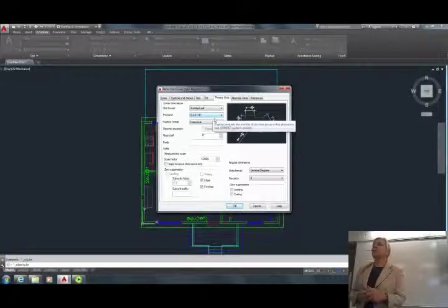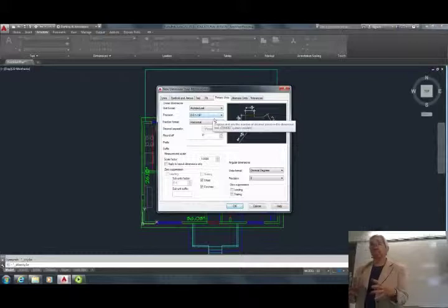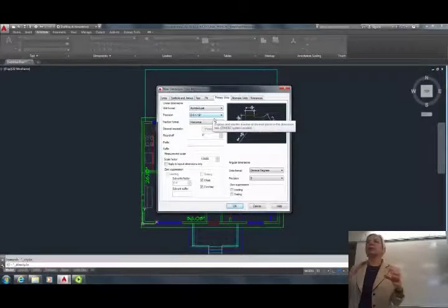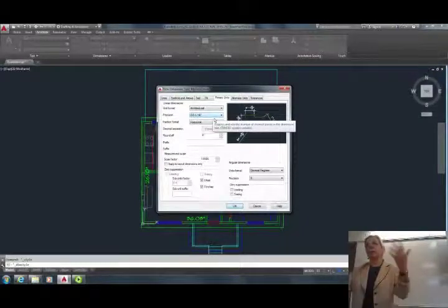Okay? So in real life you would do that, because if you're getting a bathroom that's 4 feet, 9 inches, and 3/4, you know your tub is not going to fit. And you've got to change that dimension. So if that's what you drew, you should change it to 5 feet. I like to make it even a little bit more than 5 feet in case my contractors mess up and I don't get 5 feet clear. And if you're going to change the dimension but not redraw the geometry, then you have to remember in real life that something has to give along the string, or your dimensions don't add up to overall house dimension.